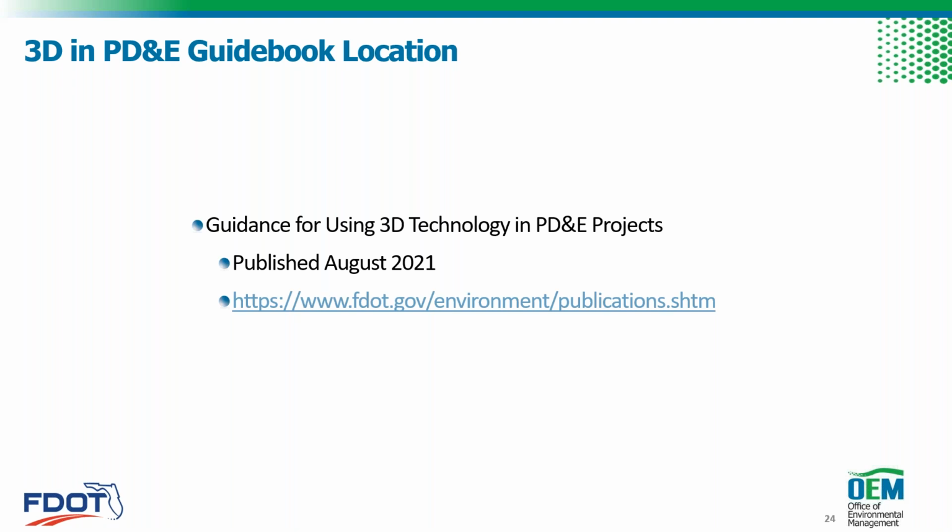However, vertical geometry is supposed to be considered during PD&E. So when you have extenuating circumstances, or if you're going to need to look at retaining walls or tie down slips for bridges and things like that, vertical geometry is supposed to be considered in PD&E. Utilizing these 3D tools will allow that to be more accurate and more obvious.